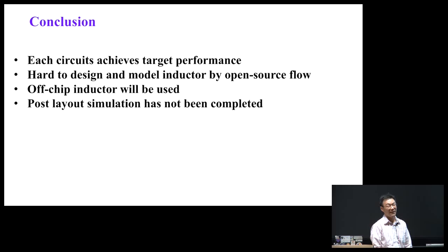Thank you for the presentation. I wonder, have you ever considered using the Skywater PDK on Cadence Virtuoso? Yes, that's a really good question, because for really accurate simulation such as phase noise, the open EDA tools didn't give us accurate results. So only for the phase noise simulation, we migrate to our server with the OpenPDK, and use licensed tools such as Cadence Virtuoso. Noise was my second question, but you already answered it.